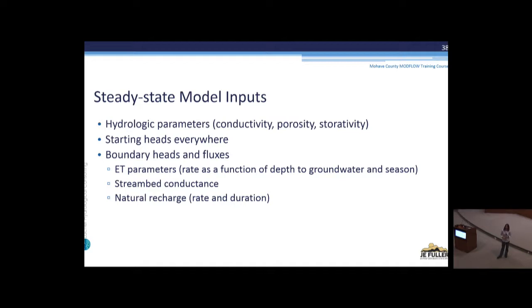We think of natural recharge as being sort of the average over a century or something. We're seeing now that natural recharge has a period of oscillation of some sort, and that may be 50 to 100 years. We don't really know. So when we just hold natural recharge constant across all our transient models, we can run into problems with that.